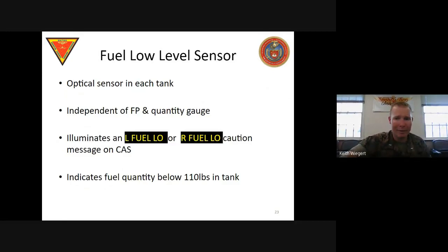If it happens, that's fine. Fly the airplane, right? As soon as you level back out in the downwind, the fuel is going to come back to cover up this eyeball, and it'll turn the light off for you, right? Because the fuel's covering it back up again. It freaks out sometimes. Again, it's just the nature of having liquid fuel in an aircraft, right? But I remember the first time that happened when I was flying the brake and coming into land at home field. I was like, "What the fuck is that?